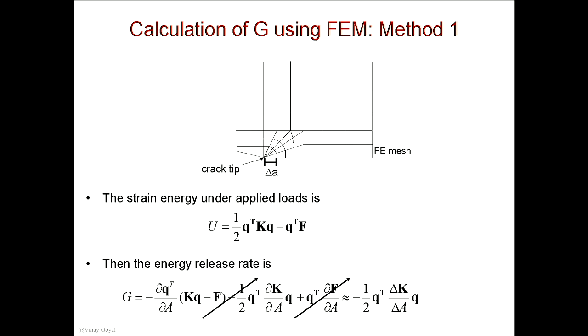And the strain energy is supposed to be quadratic. Doesn't this look quadratic to you in nature? So it should look quadratic, and when it's not quadratic anymore, that's when buckling is starting to occur. So you can actually use that as a measure as well. I showed you some other ways in the previous lecture, but you can also use strain energy. So strain energy can also be calculated in the problems that you actually solved in class. Once you have the deflection, you know the stiffness matrix of the whole system, this is fairly easy to calculate.